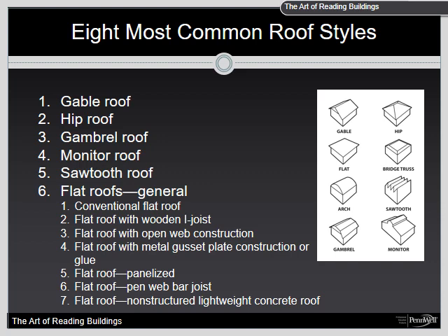Older gambrel roofs are likely conventional construction, and newer gambrel roofs may use lightweight construction. If lightweight construction is present in the roof, it was also likely used in the construction of the floors. If there is a noteworthy amount of storage in a gambrel loft area, this could be a significant hazard for personnel working below the loft area.